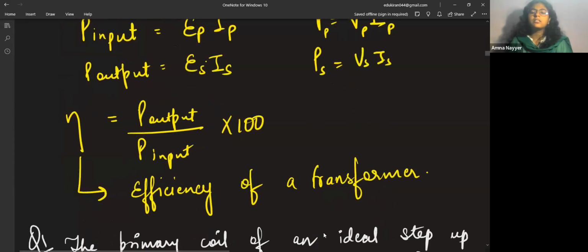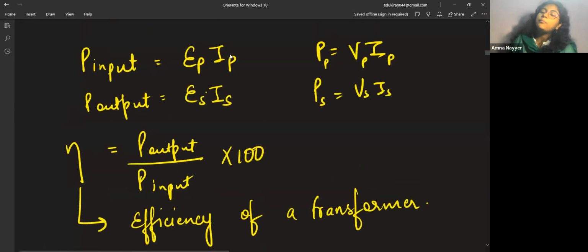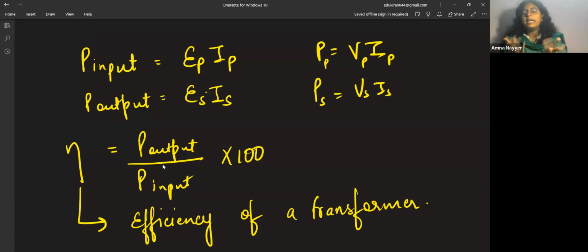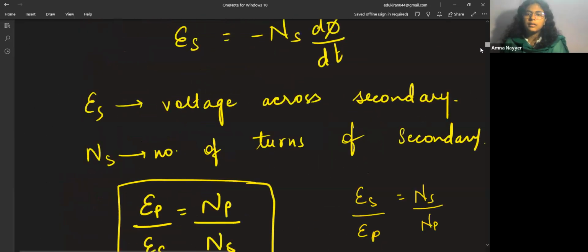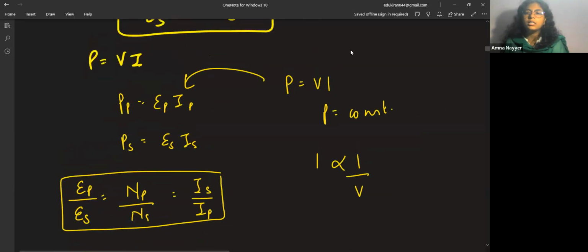One question we have to discuss. This we'll discuss right now only. So power is this. Input power means the power of the primary one. And this is output, power of the secondary one. Efficiency of transformer is output power, meaning what has been generated, divided by input that has come from the primary, into 100 to get it in the percentage form. That is known as efficiency of transformer. One question, let us see, based upon this, all the parts will help in coverage of all the formula. Quickly write down all these formula. One question we'll see.